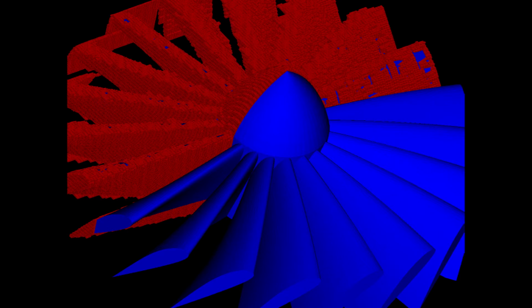Now, for low speed flows over small objects, the Reynolds number is relatively low. For a large object at a moderate speed, the Reynolds number is very high, and for a large object at a hypersonic speed, the Reynolds number is extremely high. In order to simulate a fluid flow over a vehicle, a small region, usually called the domain, is subdivided into a large but finite number of small cells.